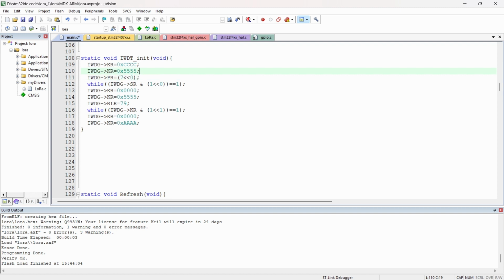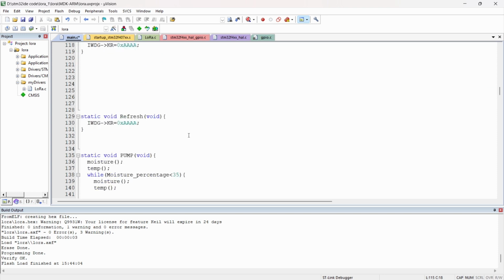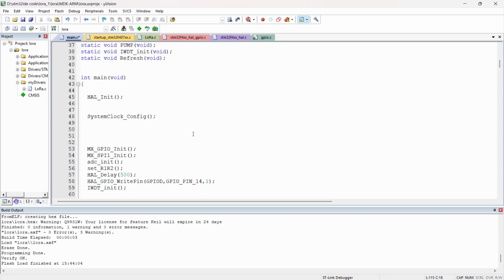So what we have done now is we have given this prescale value, right? We have left shifted this 7 to the 0th bit, so now it is 256. The next thing we have to do is give this value here, 1249. This is the value we have to give for reload, because this value is obtained by the formula. Okay. So next we are going to alter these codes.